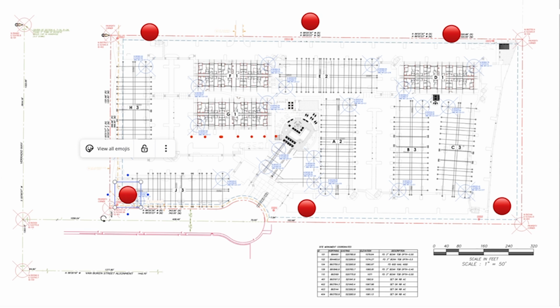And what will happen here, and forgive my sketches. Oh, no, you know what I'll do? I'll actually go into my drawing function over here. This is pretty cool. What we'll do is the surveyor or the field engineers on site will backsite a longer backsite and then shoot the ends of the points along the baseline, then do forward and back, a direct and reverse, and a forward and back pass on the points to make sure that we have everything set up. And then basically what you can do is set up a total station here, backsite, turn 90, and get anything you want in the building.